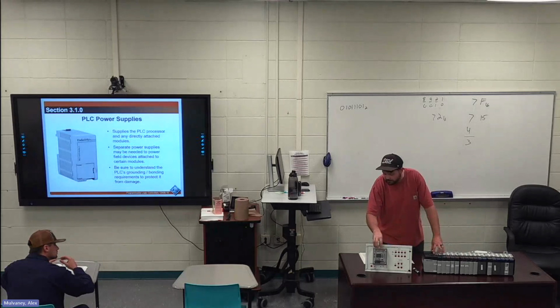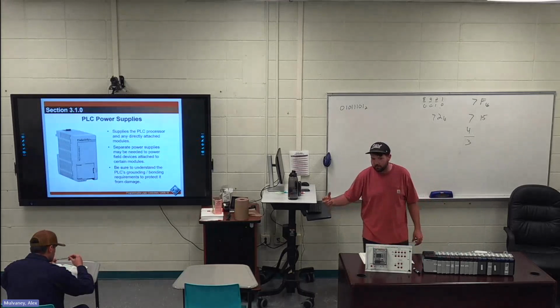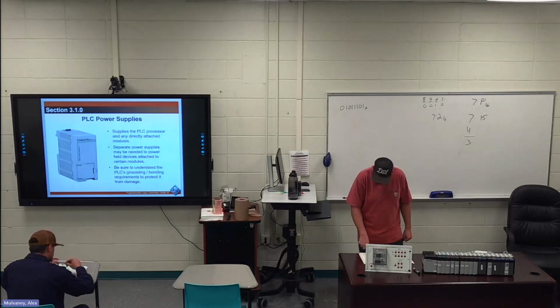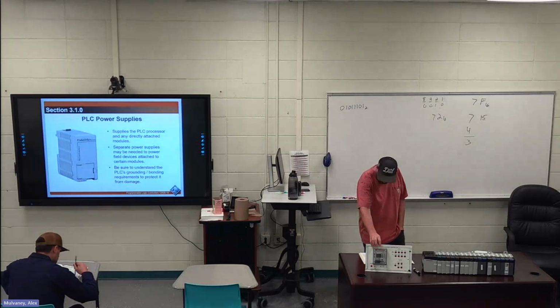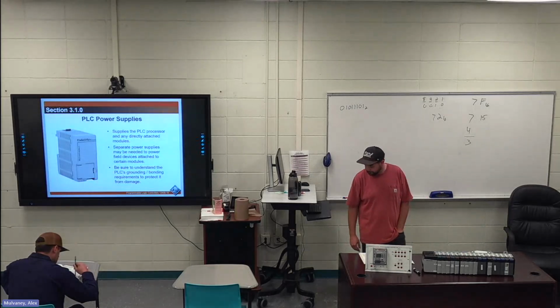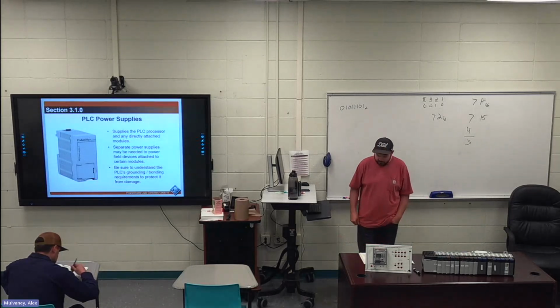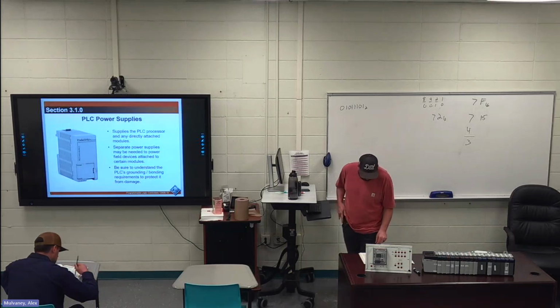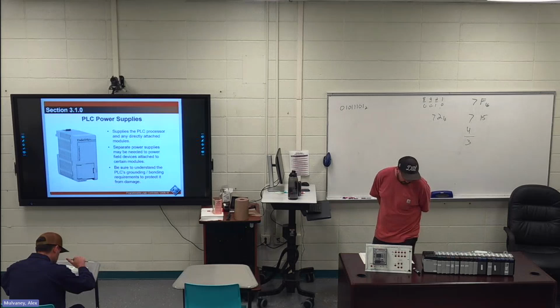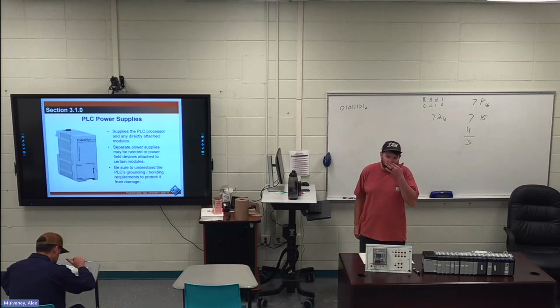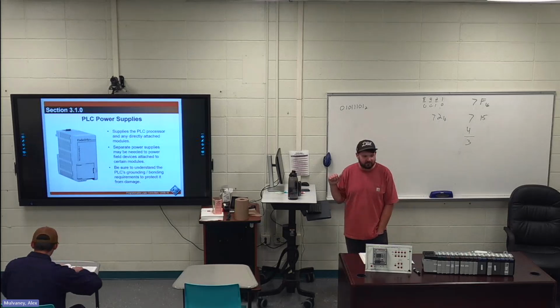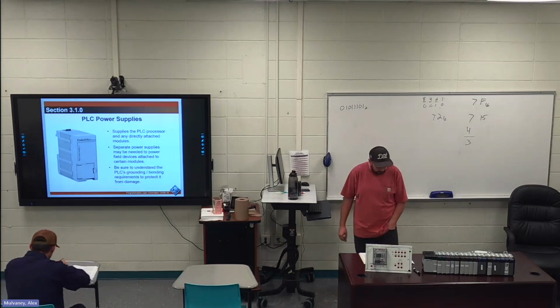The highlight was this has an internal power supply. This one has separate power supplies. It's the second paragraph at 310, right in the middle, second sentence. For very small PLCs, power supply is often internal. Last sentence on the page is highlighted. The voltages used by electronic devices found in most common control circuits are very small, often 5 volts DC or less. A lot of stuff is 5 volts that we use in the instrumentation world.